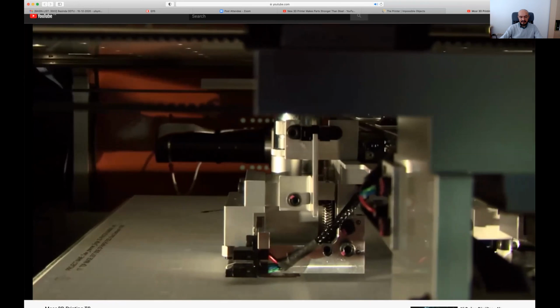The process that we have invented is called selective deposition lamination, or SDL. And as the name suggests, we selectively deposit the adhesive. So what that means is that on the very first layer, we apply adhesive, but in two different ways. On the waste material, we put down a very low density adhesive. And on the part itself, we put down a very high density adhesive.